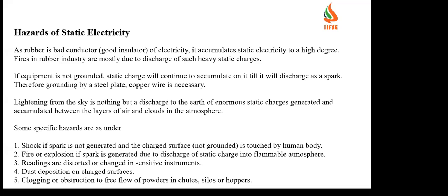And if the equipment is not grounded, the static charge will continue to accumulate on it, and eventually it will discharge as a spark. That is, where equipment is not properly grounded, due to friction, contact with surfaces, separation, or machine function, it will get generated more, and whenever it has a chance to discharge, it will discharge with a spark. Therefore, grounding by a steel plate or copper wire has to be done at any cost.